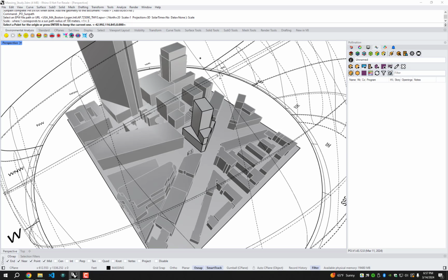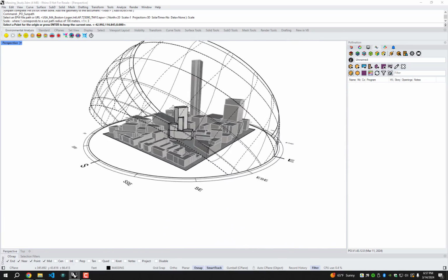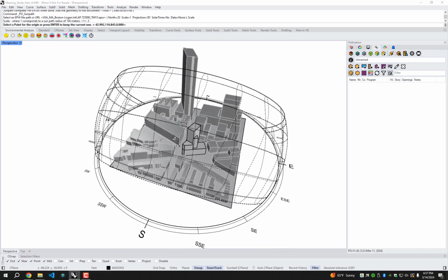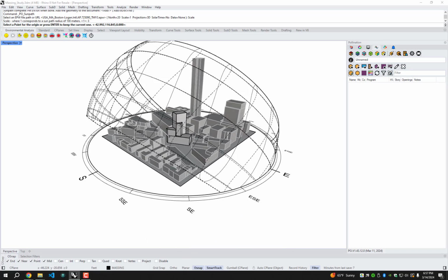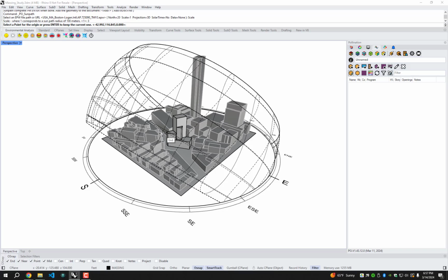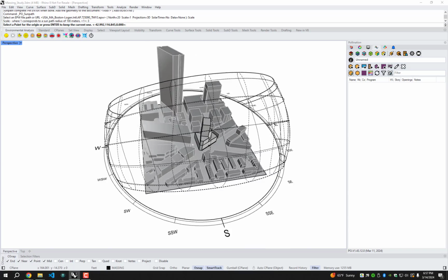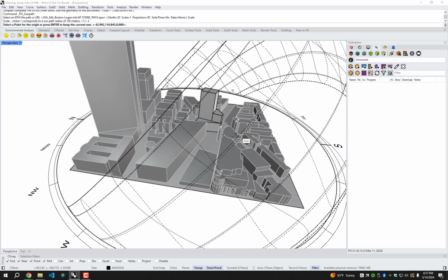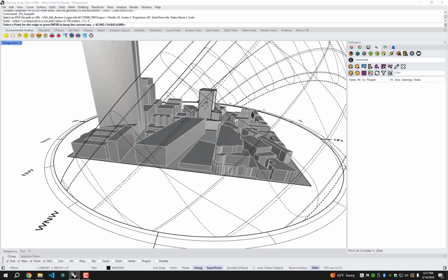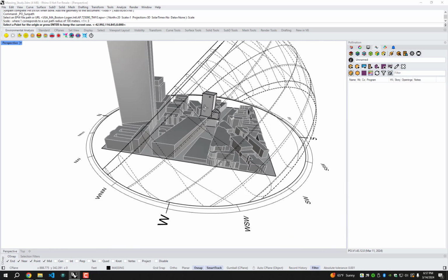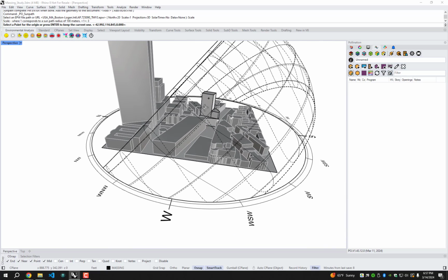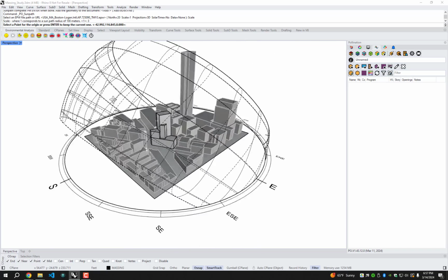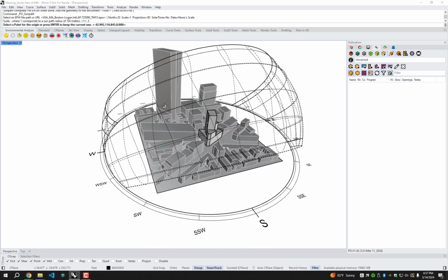And I think all these other ones make sense, but you can see you can control the scale of that Sunpath. You already saw that you can control the origin of it. So the general idea is that you can use the Sunpath essentially any time you'd want to illustrate to a client or a project manager something about this particular design. Let's say I want to show them that you're going to have to be worried about glare on this facade of this design, so you may not want to do it all glass with manual blinds unless you want those blinds to be down all the time. You can do that simply by pulling up the Sunpath here whenever you want.